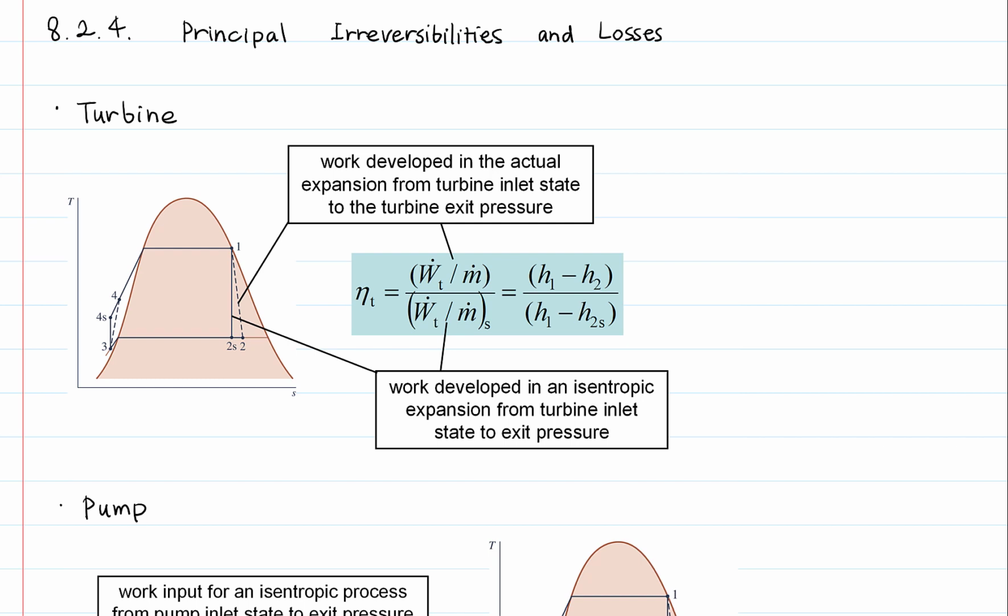Previously, we assumed the isentropic processes in the pump and the turbine for the ideal Rankine cycle, but the actual pump may require a greater work input, and the actual turbine produces a smaller work output due to the irreversibilities. The isentropic efficiencies are defined to compare the performance of the actual devices to the ideal devices.